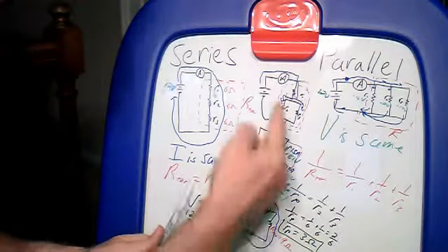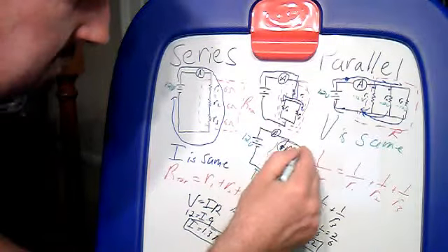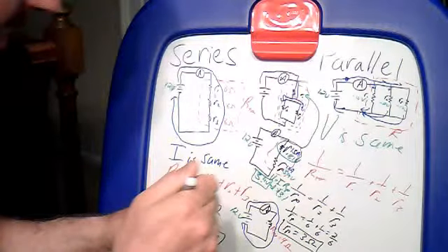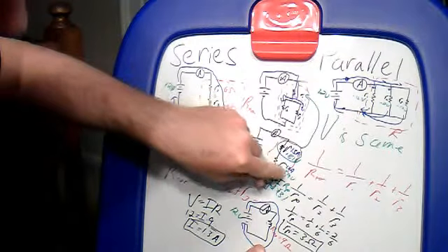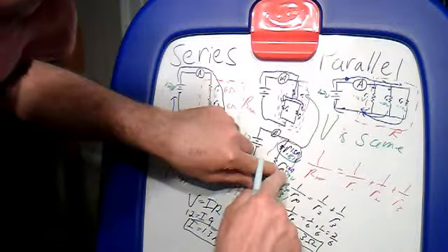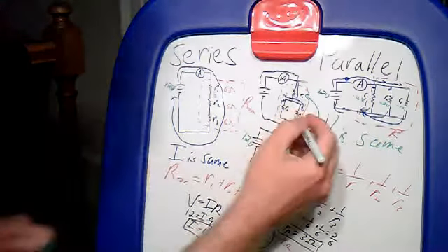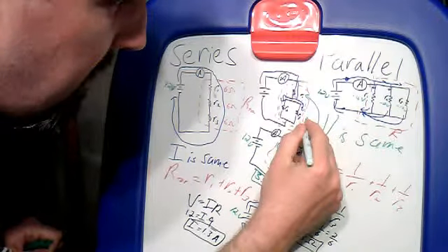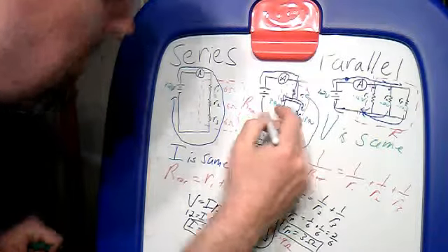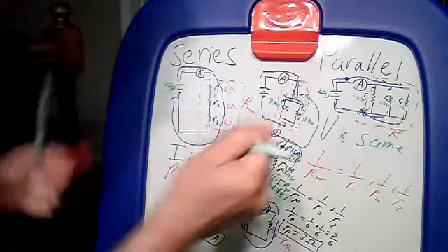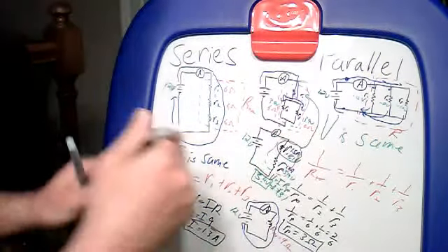So now we go back up a level. R1, we're already done, because that doesn't change. All the stuff that's true here is also true right there. But RP is really these things. And we know the current for RP, we know the voltage for R3 or RP. But really they're parallel, and the current's not the same, but the voltage is. So we now know for R3 we have a 3.9 volt drop, and for R2 we have a 3.9 volt drop.